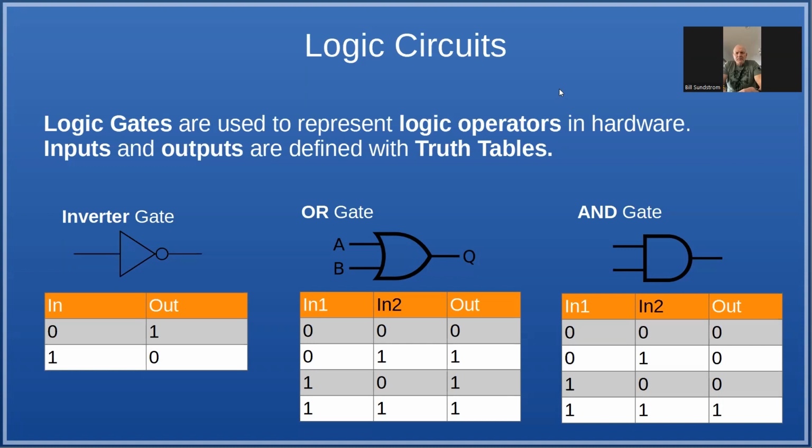So we can buy logic circuits or integrated circuits that have these elements packaged in them. Like in the case of inverters, there's usually a hex, six inverters, in a normal package, in a 14-pin package. Yes, it's 14. 14 is 6. Right? Yeah. Power, ground, and